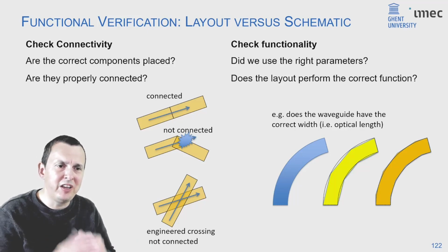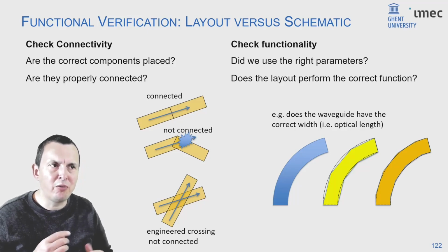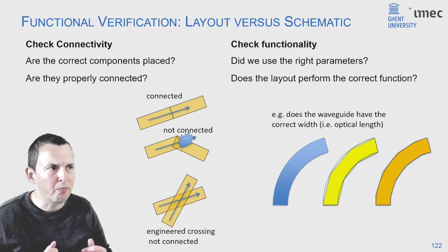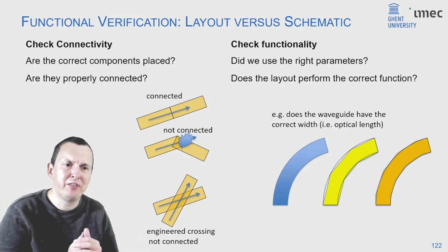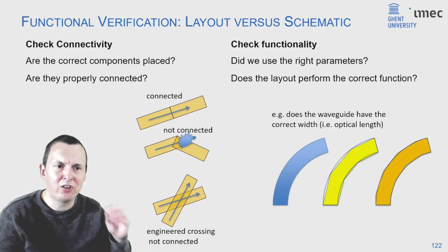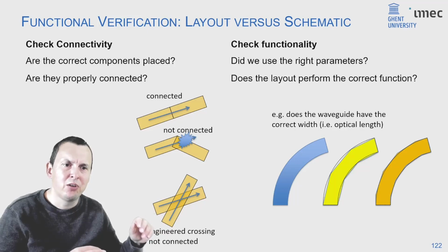So these special cases for photonics you need to be able to pick them out. Connectivity checks are slightly different in photonics than in electronics, but now we already see that quite a lot of tools offer this kind of connectivity check. A much more difficult part of the verification is to check whether all elements in your circuit will actually perform